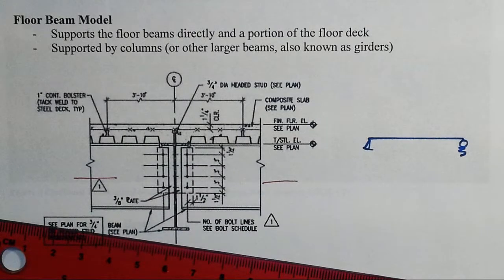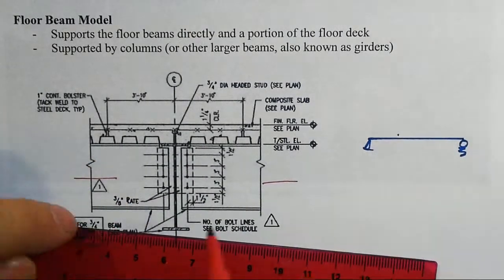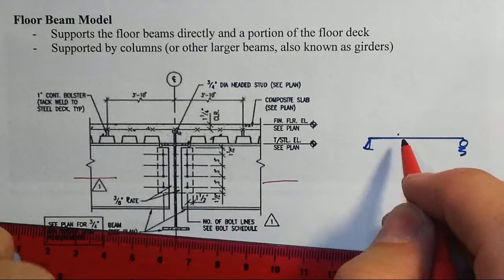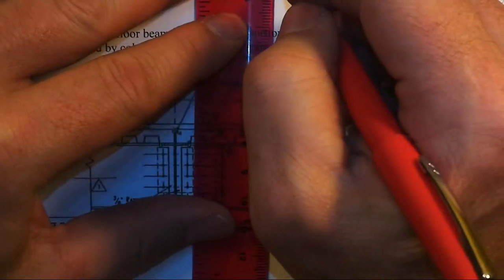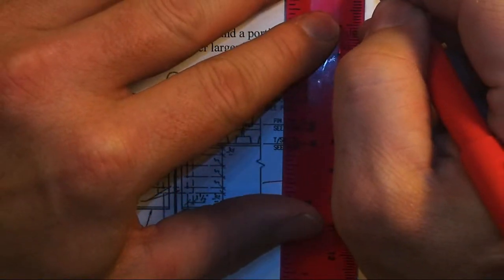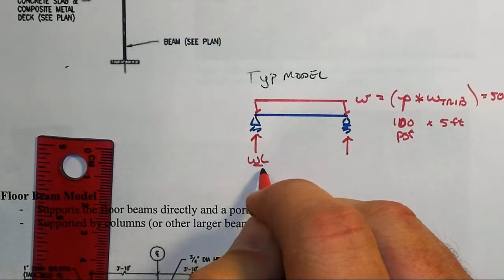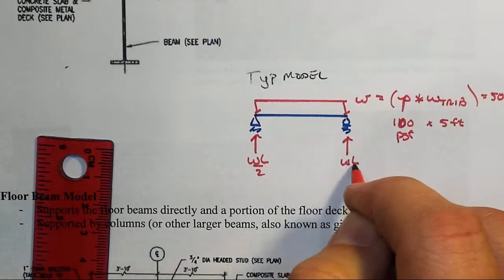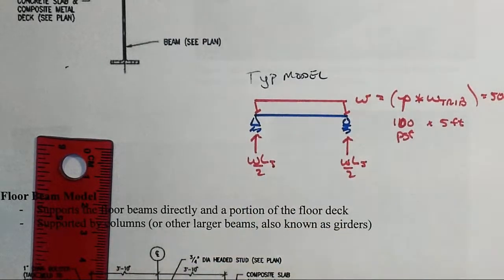Here's this new beam that's framing in, and we've got this one of these others framing in, maybe right here, maybe right there, and the reactions that we would get over here, that would be WL over 2, WL over 2 of the joist, right?